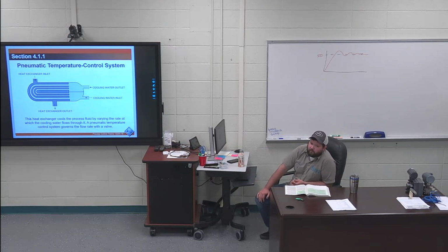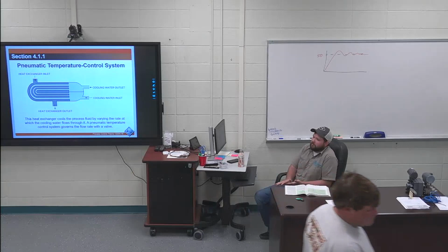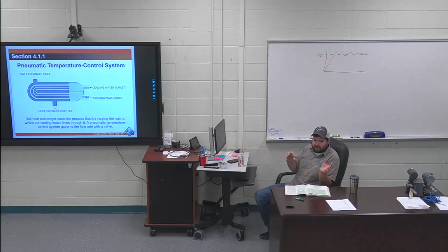This would be true, like where I come from, in the steel mill. I told you all we made big coils of steel. In the reducing mill, they just ran that big coil of steel back and forth, and each time they ran it, they pinched the rolls a little bit closer together, and that way it flattened out the steel, which made it longer. They could run up to like 3,000 feet a minute, which with a big coil of steel is fast.